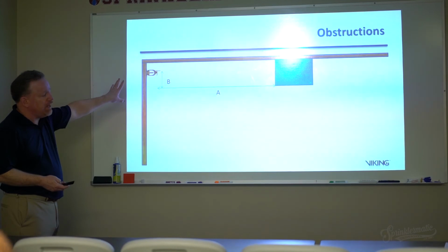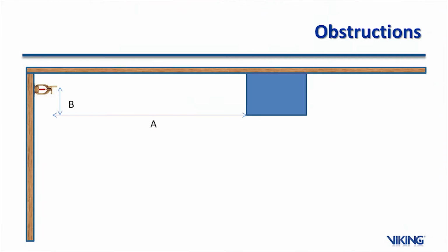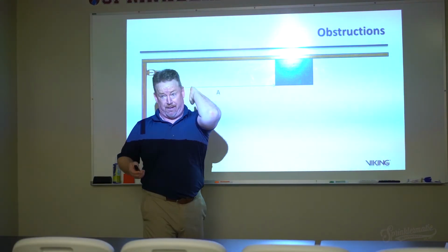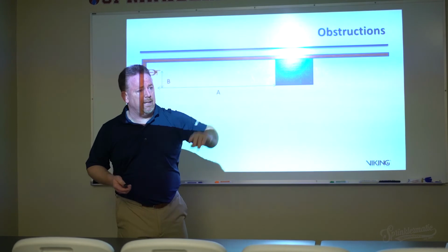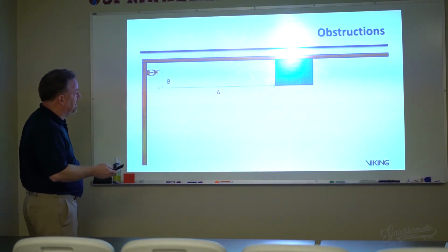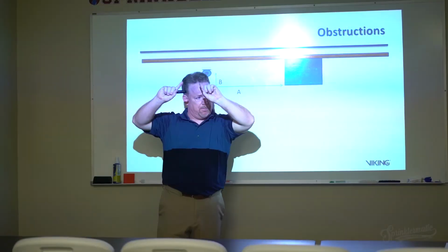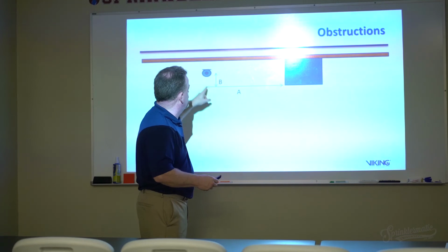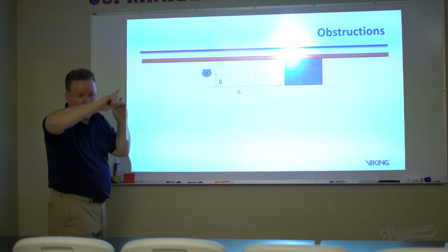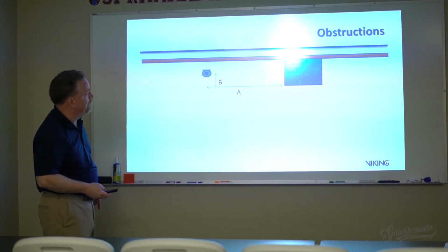Same general principles, but the beam rule has a slightly different application here, because the obstruction could exist out in front of the spray pattern, but also along the sides, because the spray pattern develops along the side. So the beam rule is applied both in front, in the spray pattern that goes out, as well as in the spray pattern that goes down the wall.